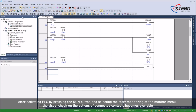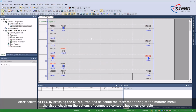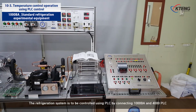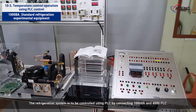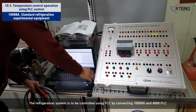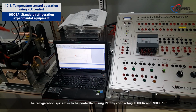After activating PLC by pressing the Run button and selecting Start Monitoring of the Monitor menu, the visual check on the actions of connected contacts becomes available. The refrigeration system is to be controlled using PLC by connecting the refrigeration equipment and PLC. Prepare a refrigeration equipment, a PLC practice equipment, and a laptop PC.